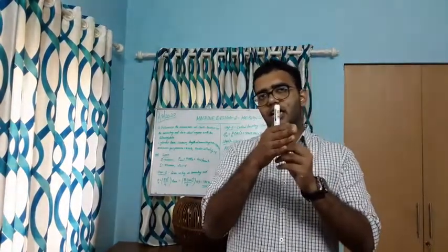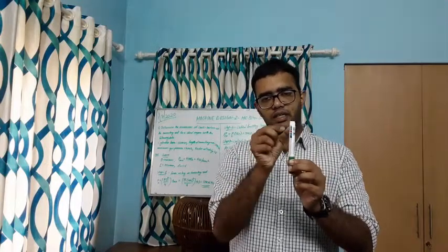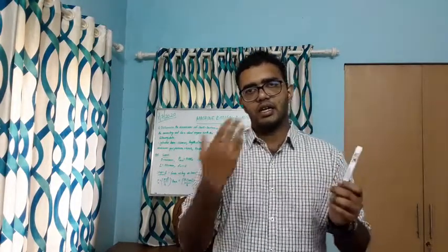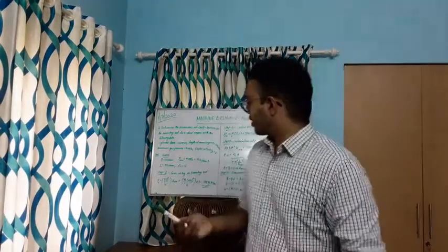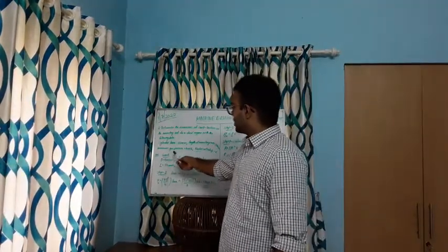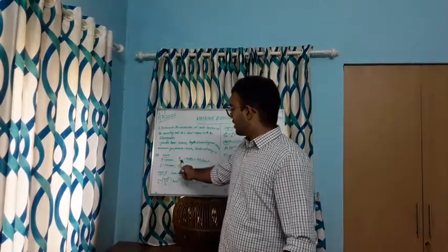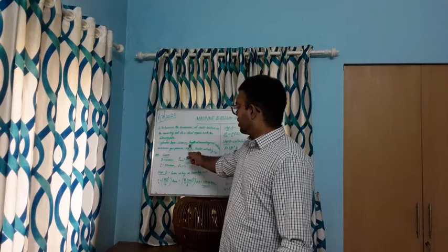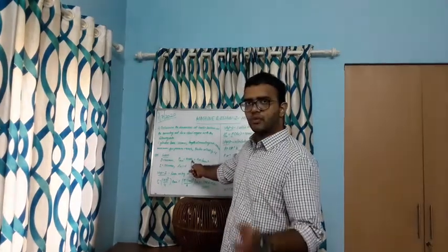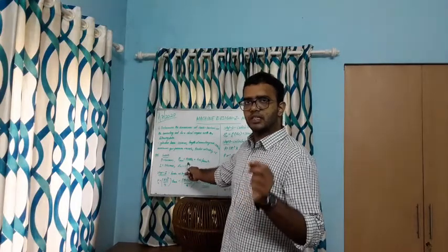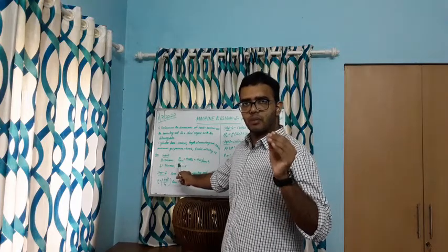When we take a connecting rod, there are various dimensions like length, breadth, width. We need to find these dimensions. They have given the data: D is the cylinder bore diameter, and P max is the maximum gas pressure, that is 4 megapascal. We convert it to Newton per mm square since it's a pressure, a type of force per area.